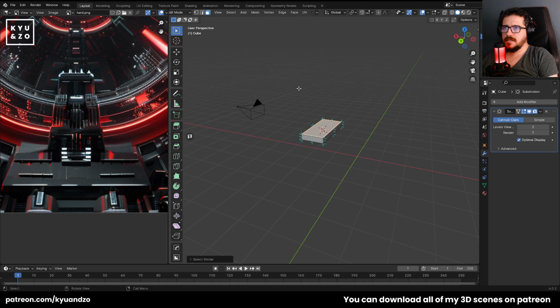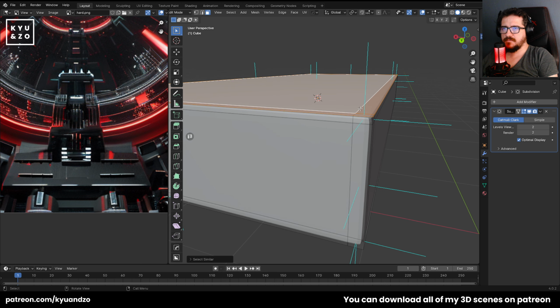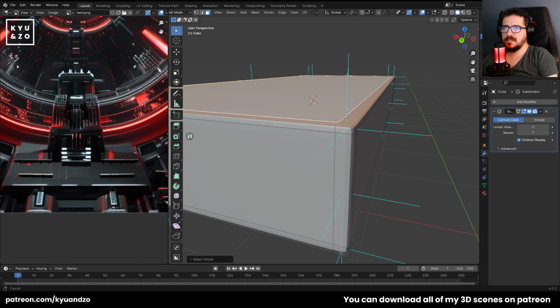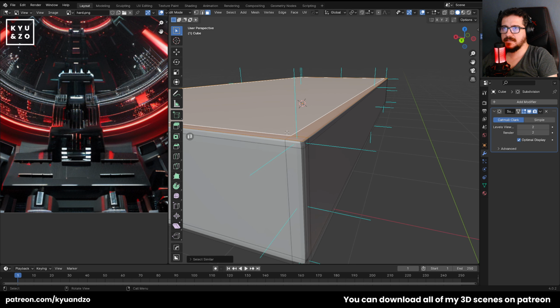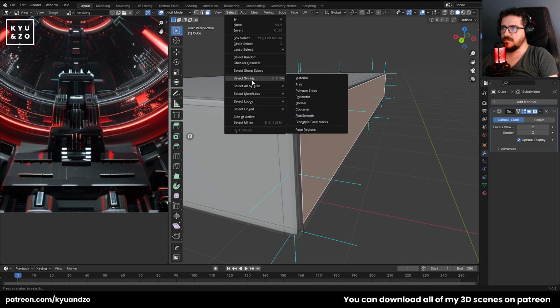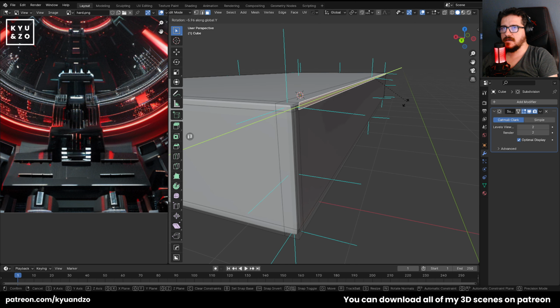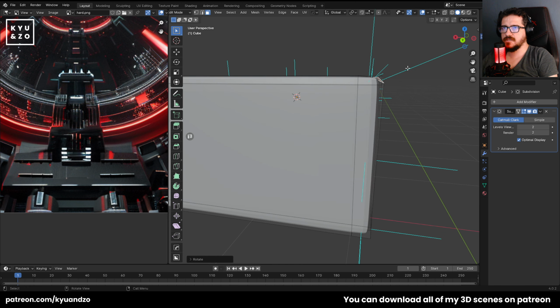You can activate it just like this. This is the normal facing. So it means that all of these lines are the faces looking the same line here. So that's why it's working. So select similar normal, and you can select the same angle. You can try it out with different experiments just like this.